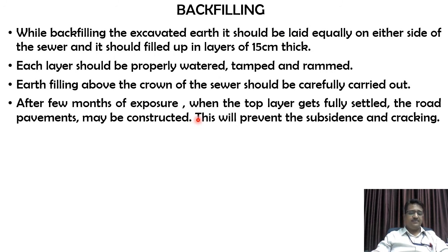Now the last step for the laying of sewers will be the backfilling. While backfilling, the excavated earth should be laid equally on either side of the sewers, and it should be filled up in layers of 15 centimeters thick. Each layer should be properly watered, tamped and rammed.